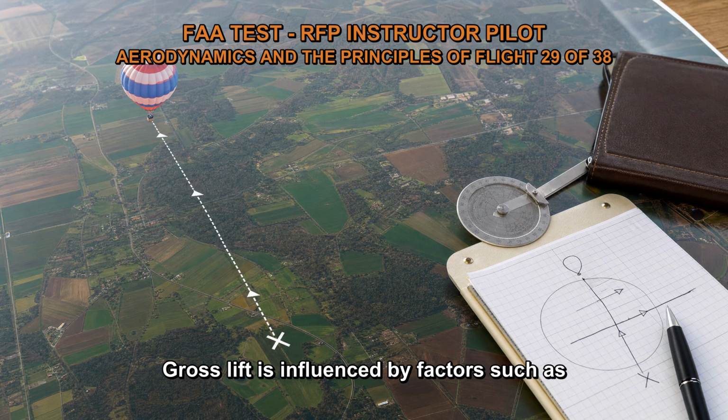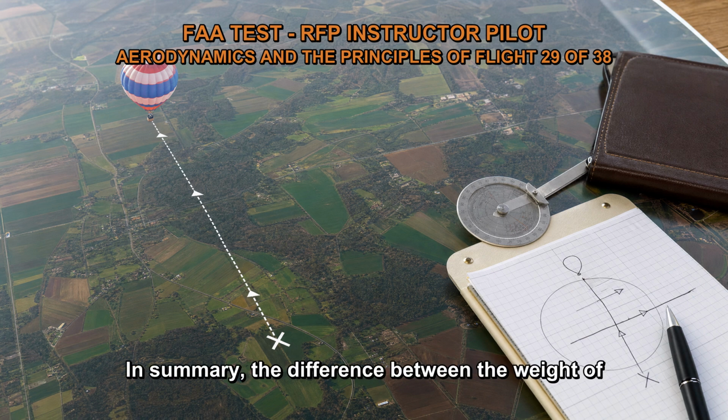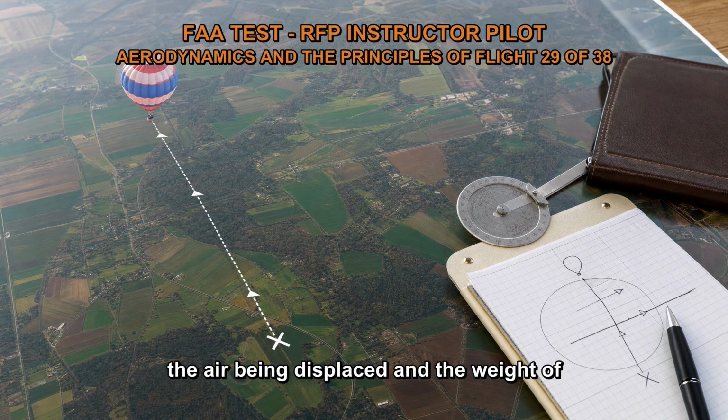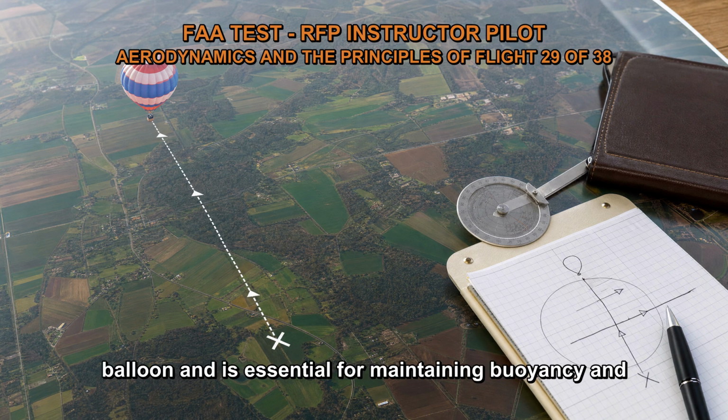Gross lift is influenced by factors such as the volume of the balloon, the density of the lifting gas, and the density of the surrounding air. In summary, the difference between the weight of the air being displaced and the weight of the lifting gas is referred to as gross lift. It represents the total lift generated by the balloon and is essential for maintaining buoyancy and flight.